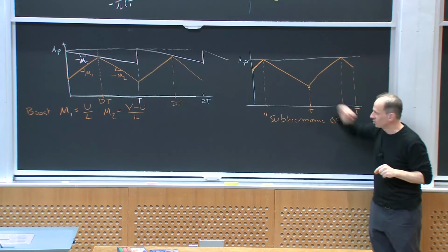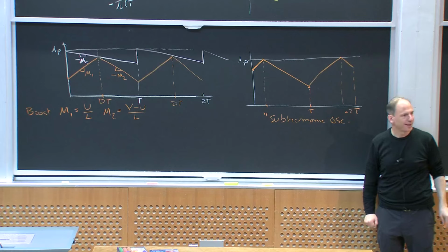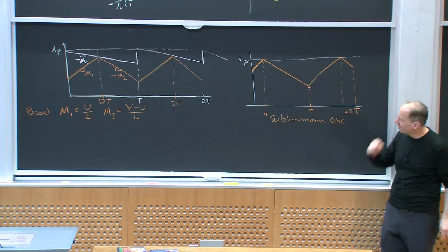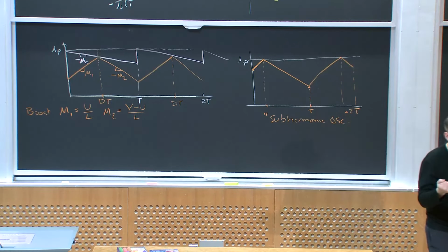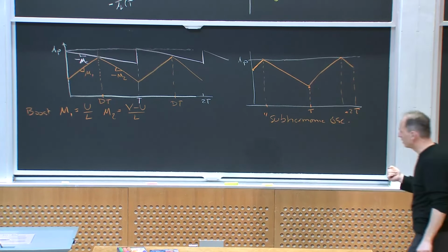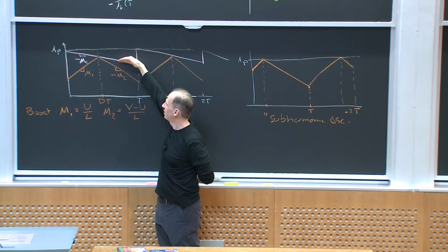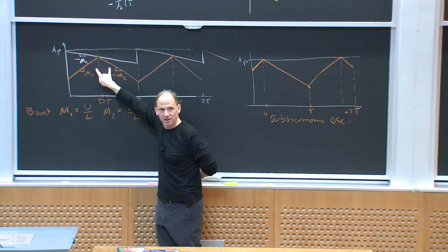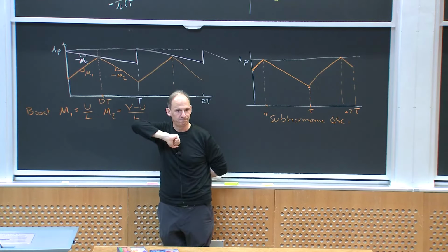Generally, this issue is called the ripple instability. This ripple doesn't settle down into periodic steady state behavior, okay? And what people figured out, and the first paper I knew about this was out of the Caltech group in the late 70s, but other people thought of it too, was to stick this compensating ramp in, which if you put enough compensating ramp in, makes that behavior go away and it'll settle down just like this case to a kind of a fixed ripple.